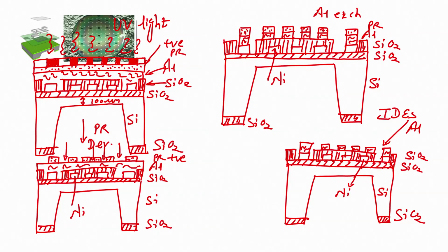Now, after this, what is the next step? The next step would be acetone dip. So, when I dip my wafer in acetone, what will I have? I will have my interdigitated electrodes over insulator over micro heater over oxidized silicon substrate, and that is having a diaphragm. Still, we have not finished fabricating a VOC sensor.